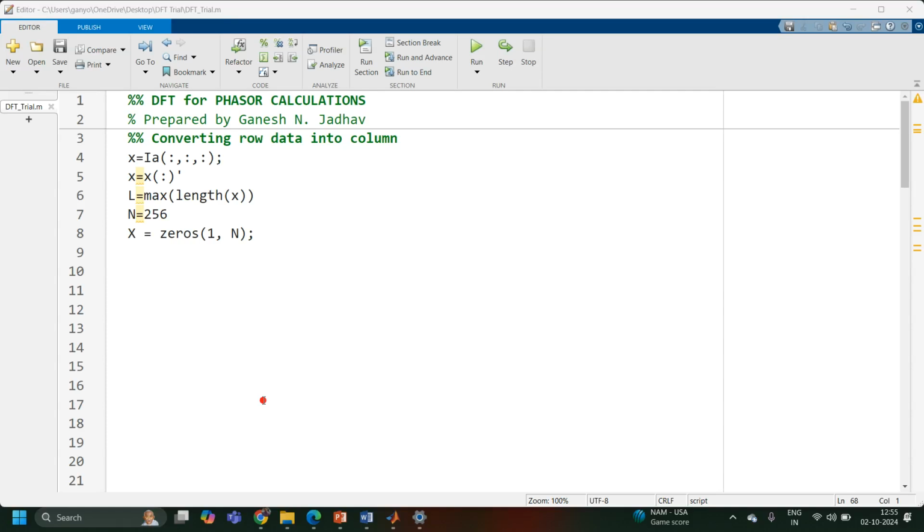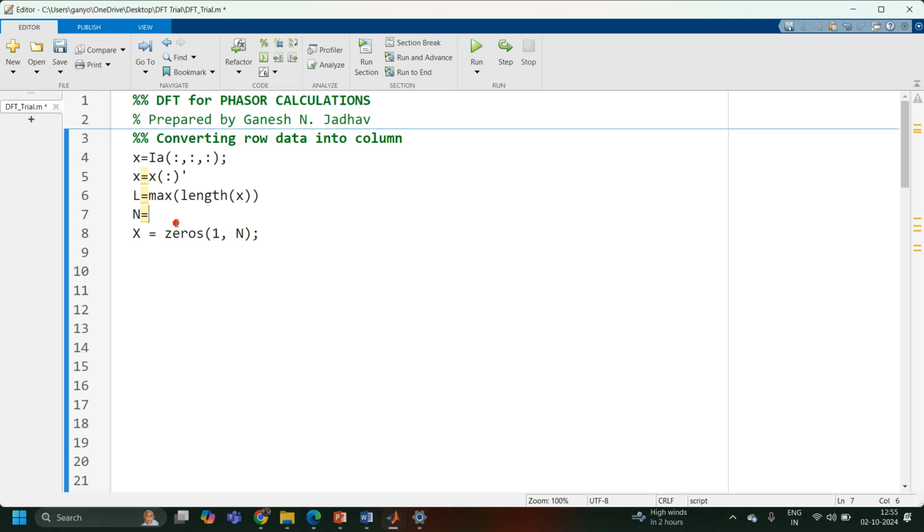Hello everyone, welcome to the video on DFT for phasor calculation in harmonic analysis. In the last video, we studied how to simulate the nonlinear system and how to store the sampled data into the workspace. Here we have taken 128 samples per cycle. So I'm making n equal to 128.